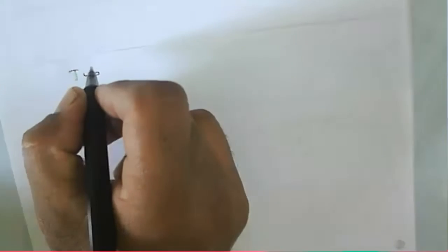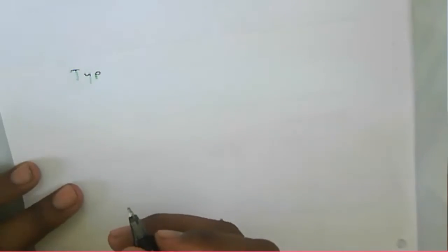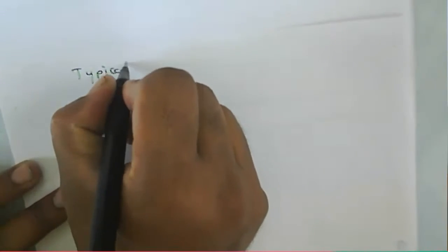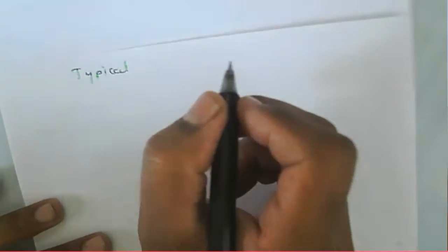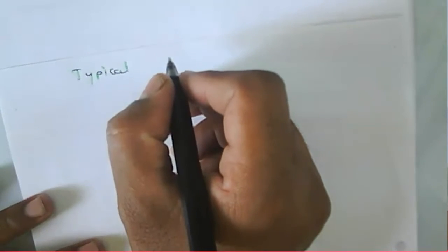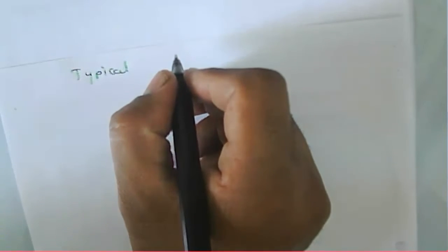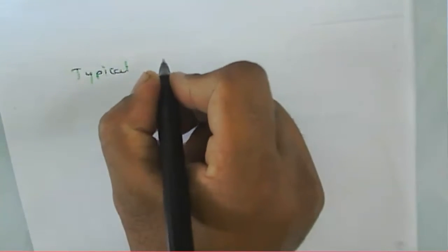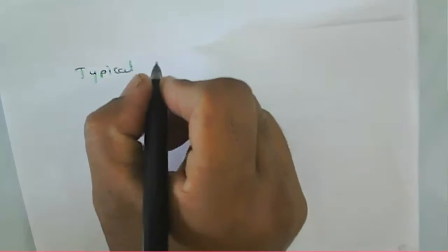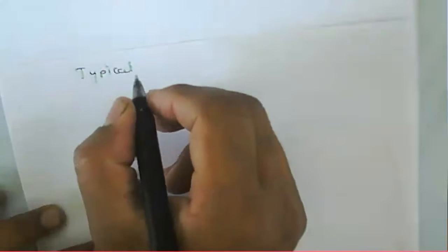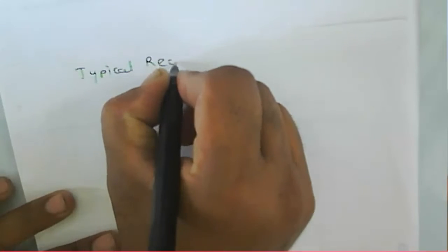In a receiver there are various components: generally an RF amplifier, a down converter, then an IF amplifier, and a demodulator. Then we have to calculate the noise power with respect to those particular components. There will be noise from each particular component. We'll see that first.